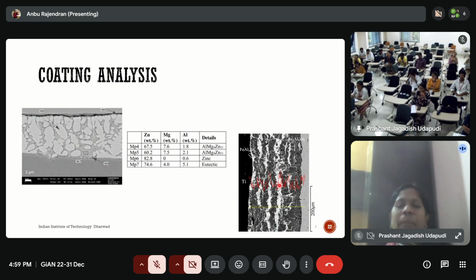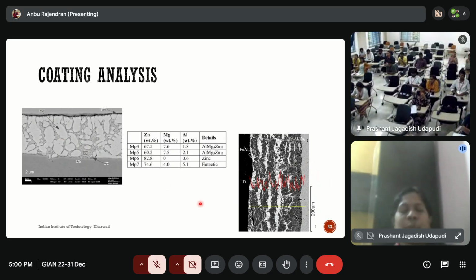Okay, so this is the pattern of titanium across this product, whatever formed over the substrate surface. If it identified some compound, how iron is distributed, how aluminum is distributed, like that individual elements you can pick, and the distribution map you can get out of it. That facility also will be provided by the SEM EDS detector.